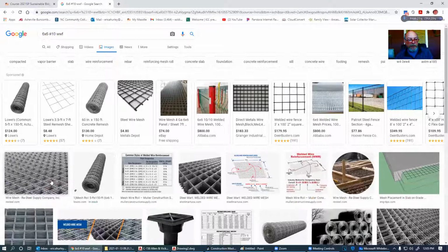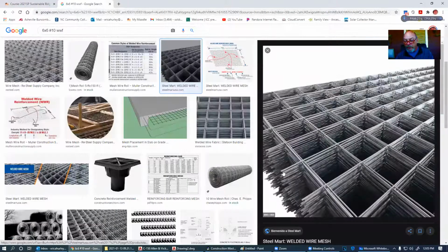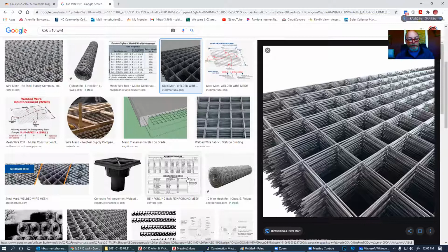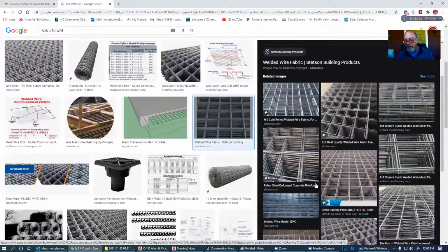And it goes into the concrete. And I promise you guys, if you ever do any concrete at all, don't buy the rolls, buy the flat stuff. This stuff tends to roll back up when you lay it down. And those ends, if you'll notice in this picture here, if that thing's coming at you at 30 miles an hour, it's going to penetrate that old skull of yours. So buy the flat stock, and you can buy these and they come in 5x10s.